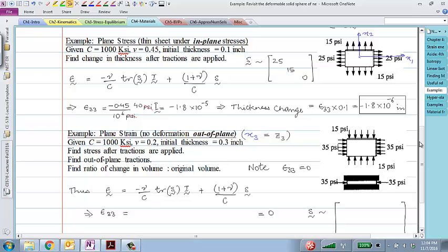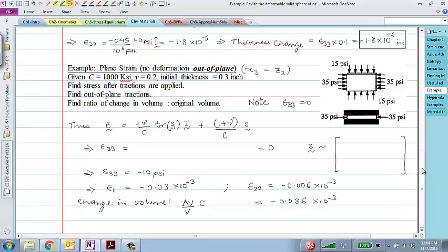Okay. All right. Let's take a look at the other problem that we were talking about, plane strain. Can somebody think of an example of where you might come across a plane strain problem? We want a two-dimensional state of strain. That is, if this is the sheet, then there should be zero displacement in the third direction.